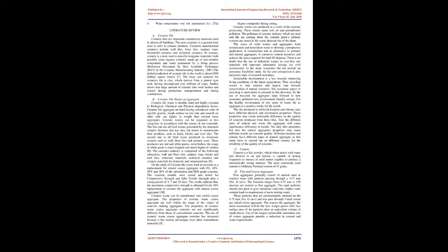5. The objectives of the study. The main objective of this study is to conclude the feasibility of using ceramic tile waste as aggregate by partial replacement of coarse aggregate. Ceramic waste could be transformed into useful coarse aggregate. The aim of this study was to produce and test M20 quality concrete with ceramic tile waste.